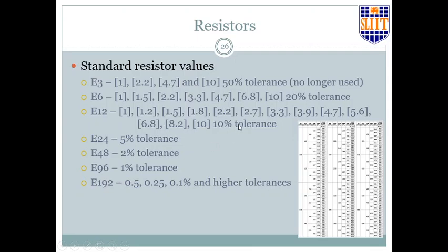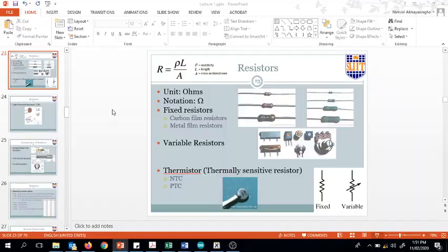Now the tolerances. Certain accuracies are allowed in the particular value ranges. What is allowed by the E12 series is 10% tolerance. So that device can have a maximum of 10% error, right? Whereas E24 allows 5% only, it doesn't allow 10% error. Let's see why. In the same way, if the error is 20% for the E12 series, that is a problem because the maximum error that is allowed is 10%. Let's see why is it so.